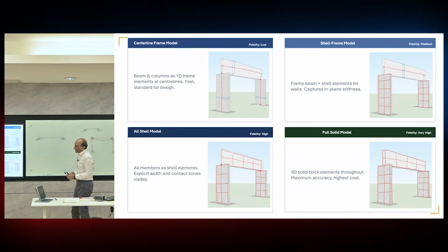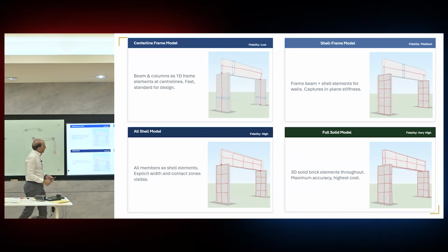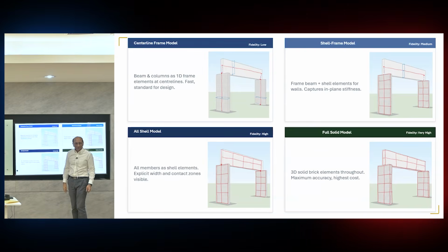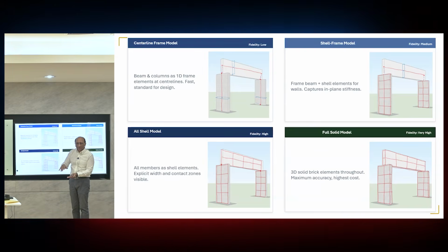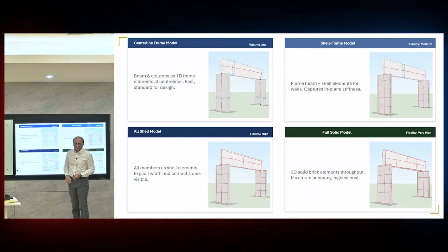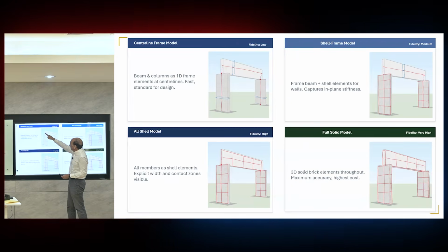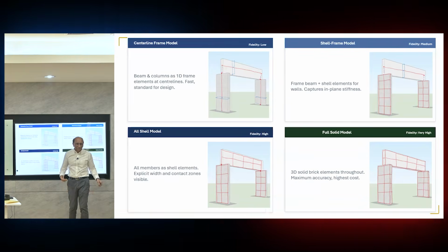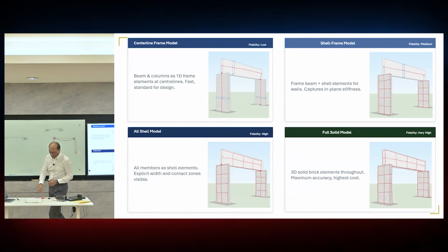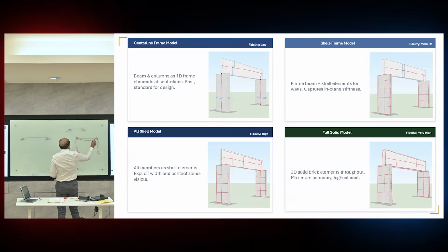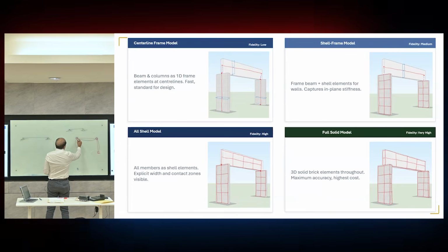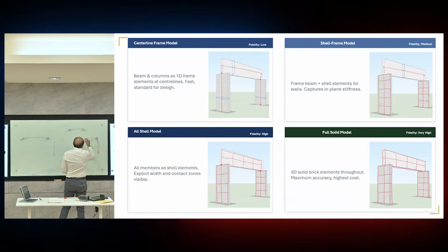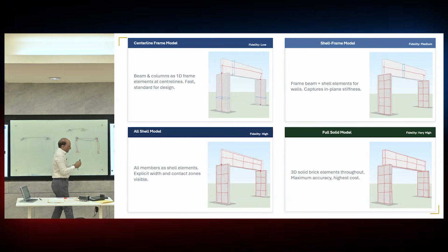So if you do that frame model, where do you place this beam? Will you connect it to these two points? That means you have effectively brought the beam down, which is physically not correct. And if you keep the center line there, what do you do with those portions? So if you want to create a frame out of this one, you think you can create a frame like this one. That's the beam, that is the wall. The wall finishes here. Beam is here. What do you do with this height?